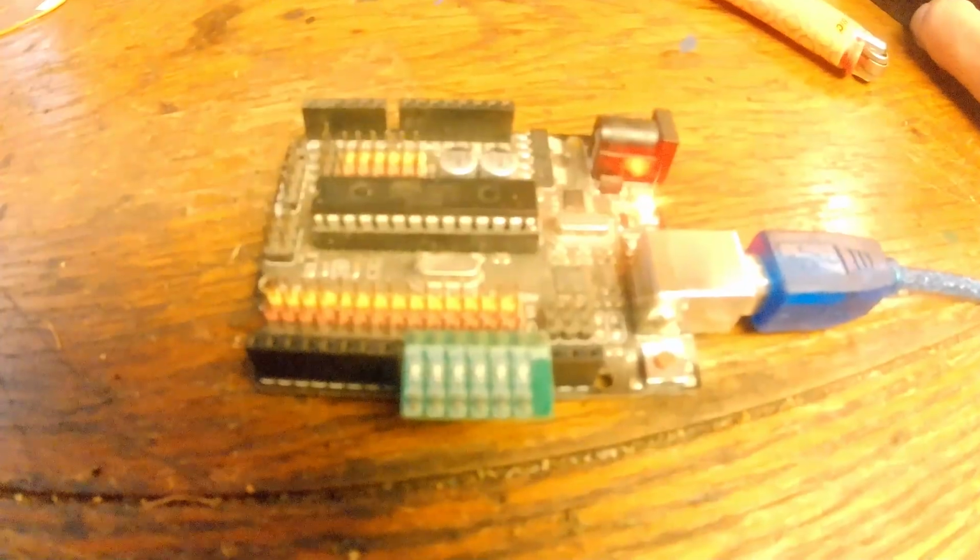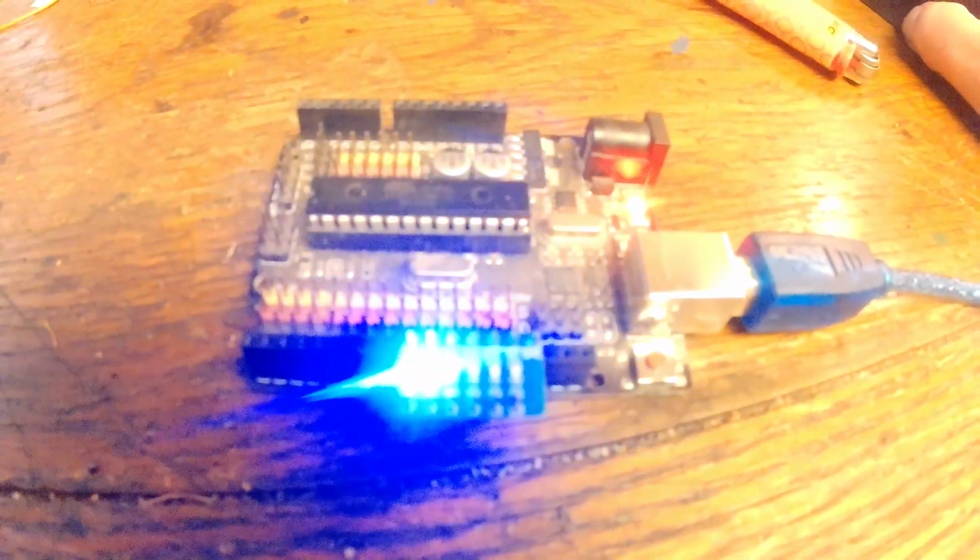And that's it. This short program demonstrates how a for loop can make repetitive tasks simple and elegant. Instead of writing 6 separate lines of code for each LED, the loop handles all of them automatically. When you upload this sketch to your Arduino and connect LEDs to pins 8 through 13, you'll see them light up one by one, stay on for a moment, then all switch off together and repeat.